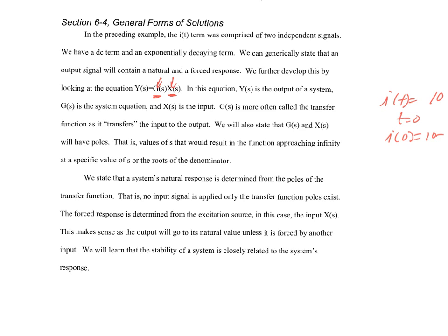If you're designing a process, filling up a tank, or moving a conveyor, that has an actual process. That has a transfer function. So I excite a tank by maybe turning on water at 5 gallons per minute, or maybe sending a control signal to a valve to open to a certain percentage. And each one of those inputs or stimuli can be modeled to have a corresponding output, all right? So the G is just how we model physical systems and how we transfer our input to our output.